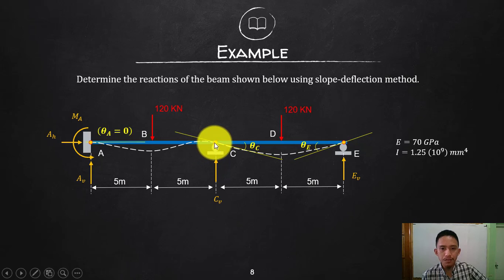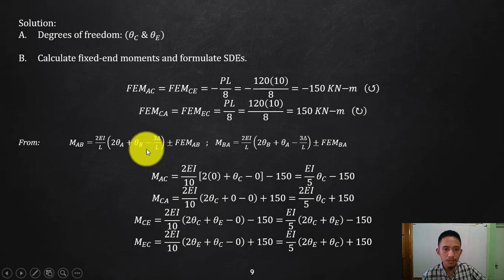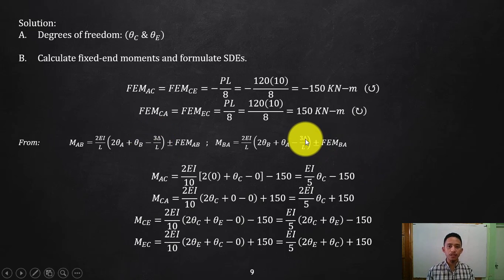But for beams, at the supports that we are considering, there are no deflections unless there is a support settlement. We actually did not discuss that one. You can read about support settlements. Therefore, in this equation, we can neglect that delta, this minus 3 delta over L. We will be using this one on frames with sways or with deflections.